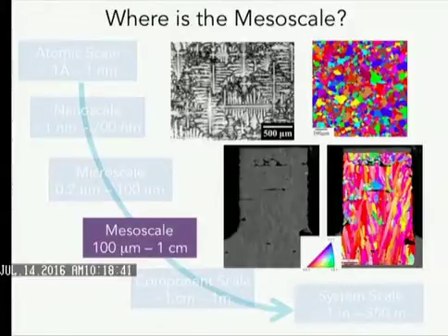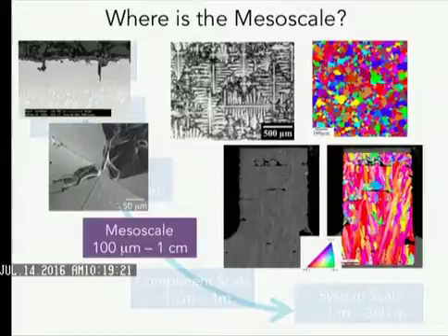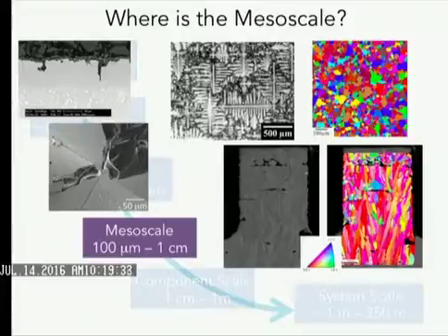I've chosen one little example here because it's such a topic that everyone seems interested in. If you now take, say, titanium or nickel or something like that into an additive manufacturing process, so now you've changed the structure of the individual crystals here, and you can see, well, maybe you didn't scan the laser right, so there's some powder particles there, and there's an associated disturbance with the structure and so forth. And so not only do we have defects that sort of come as an intrinsic part of the process, but also we have interactions with the environment. So there may be things going on at the surface, oxides forming while you're using the material, or there may be internal things that found their way into the material, which one has to sort of account for in either a probabilistic way or a more deterministic way with models.